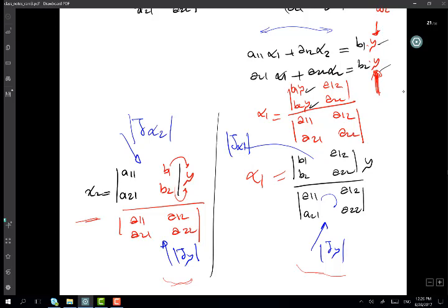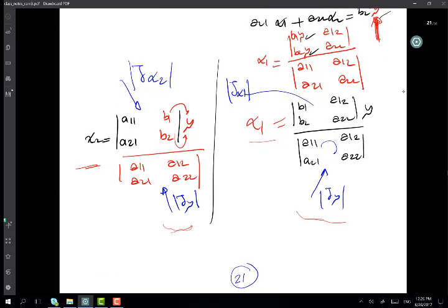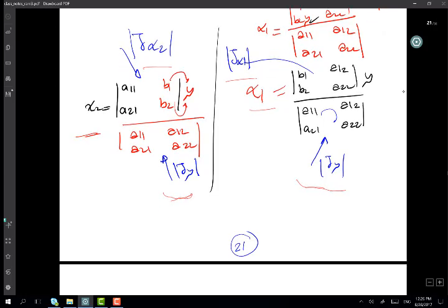Same will apply to those other Jacobians on top. So if Jx1 is equal to 0, x1 will be equal to 0. If Jx2 is equal to 0, then x2 will be equal to 0. And in our case, those will be velocities, and when we equate those Jacobians to zeros, they will give us the extreme positions of links.